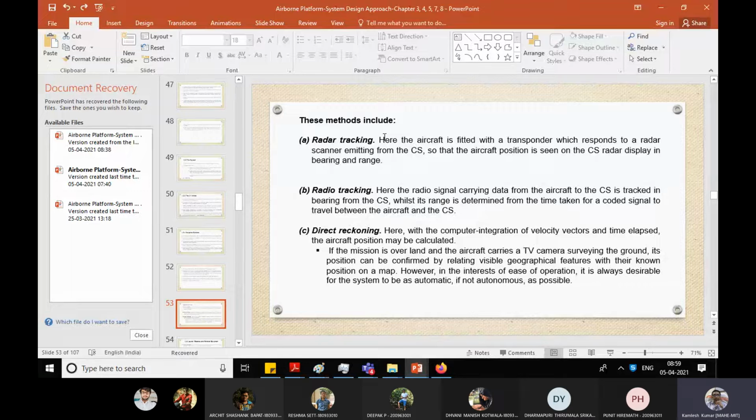Okay, so in the INS system we never talk about the axis. We talk about 3 sensors with the processor and the estimator, Kalman filter, or any good algorithms to predict the information. But AHRS is more advanced than the INS because every axis has these 3 sensors, so you are comparing every sensor with the other axis sensors. Okay, so you have at least good sensor data available on the board. Then again you have a very good processor with good software to predict that, like estimator algorithms. Kalman filter will be common to all this type of equipment.